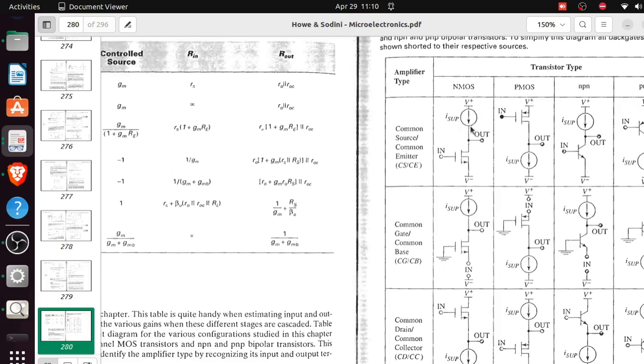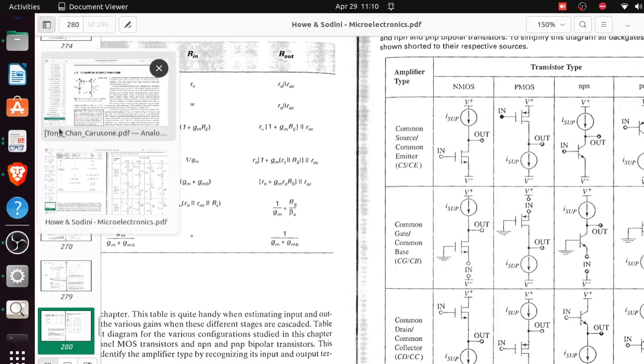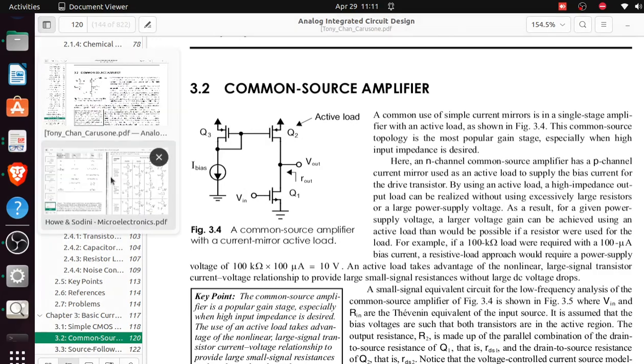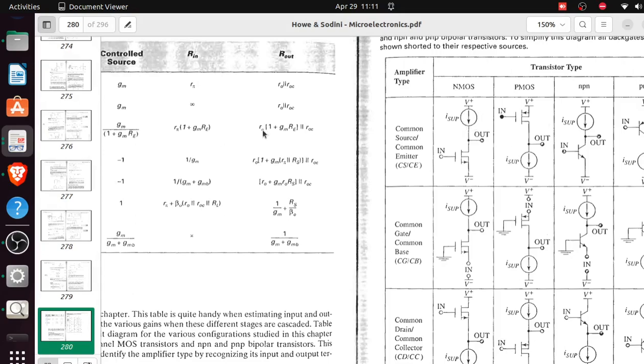So we're moving from ideal to practical design, you get. So this can just be replaced by a transistor, and the transistor you'd have to bias so that it will serve as a current source. So that's what we have here. That's the transistor. Now this is a transistor here that will be serving as a current source, replacing this current source here, right?